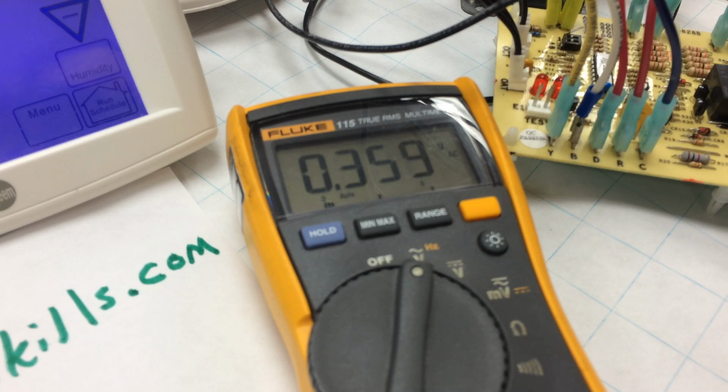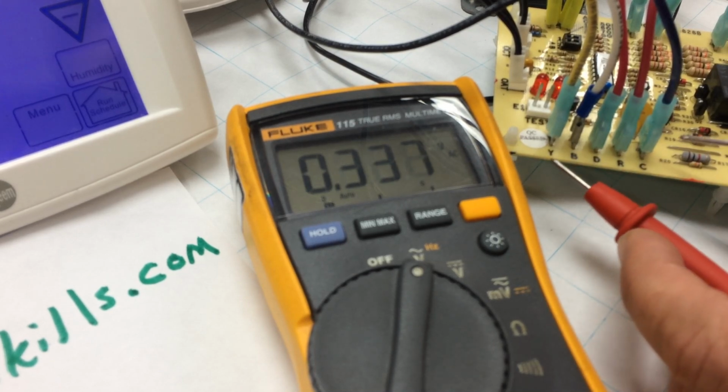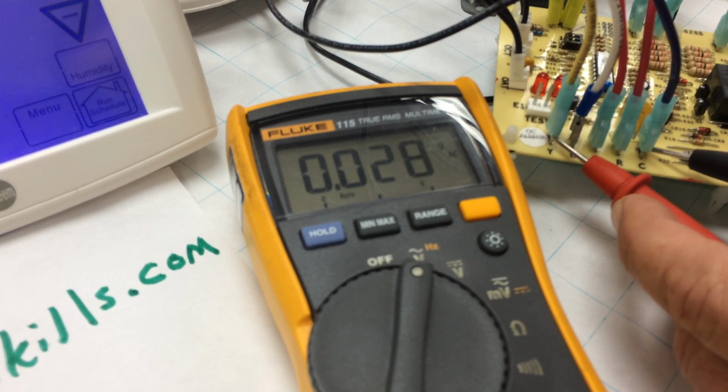If it is not in the range of 19 to 30 volts, at that point, whatever the meter is displaying, treat it like it's 0 and keep working your way back in the circuit to find where that broken wire or that open signal is. But if it's less than the minimum range that you need, again 19 volts minimum here, anything less than that, I'm going to treat it like it's zero and move on with the diagnostic process from there.